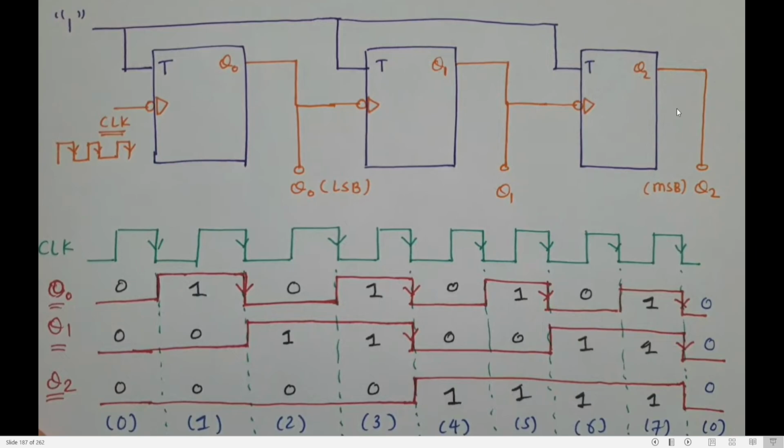So let us see the circuit. This is my circuit. I have drawn the construction of my 3-bit ripple counter. Now the first flip-flop will be given the clock. Now see the clock: pulses of positives and negatives. Done. I've drawn it. Now what do I need to do? First I need to get the output in Q0, so I will start with Q0. Now this is my Q0.